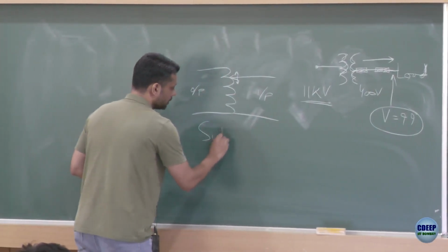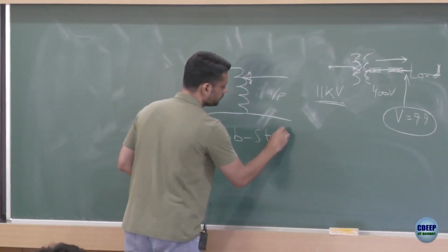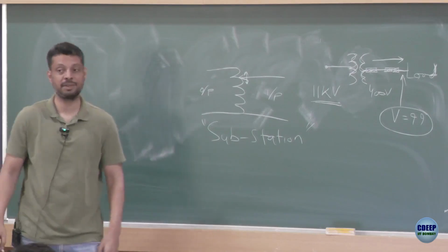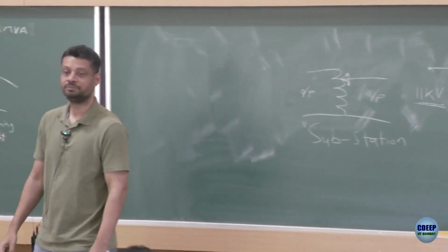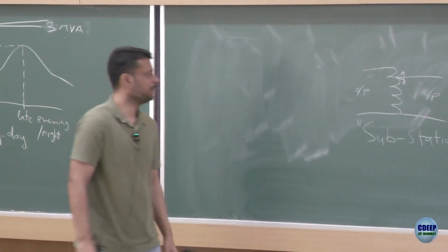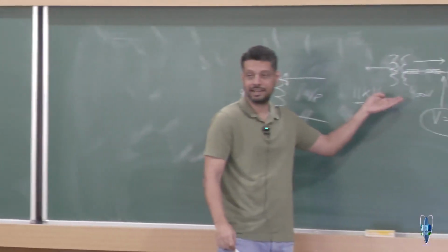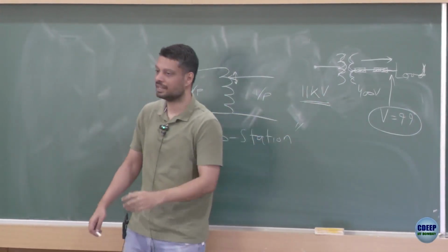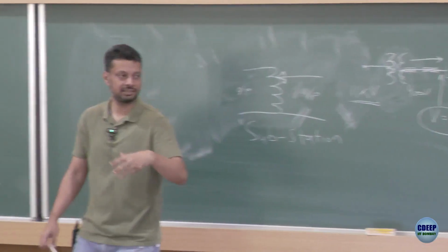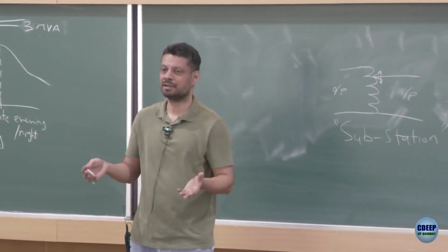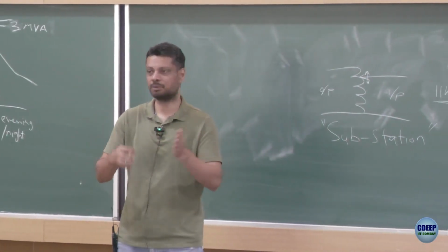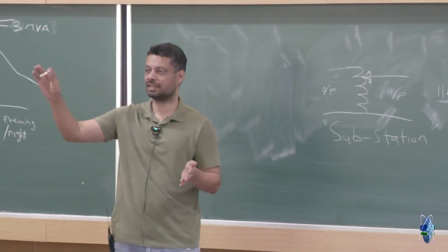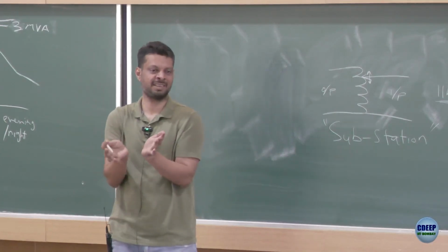Okay, new word, substation. Let's first describe what is the meaning of substation. Substation means the place where you have this guy sitting, right? That's what we call a substation. Substation means wherever you are getting a certain voltage, you are stepping it down, stepping it up, you have some circuit breaker, some overcurrent protection, and then you are passing on the other voltages towards the load side, right? That place is what we call a substation.